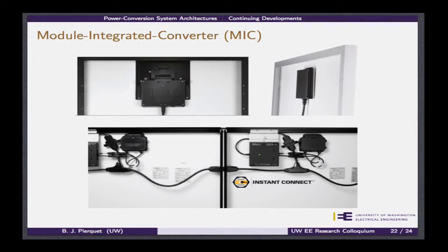So now, if you want to improve upon possible mismatches, you can deal with 20 cells at a time in series instead of 60. And so there's another benefit to going even deeper down into the module to prevent a bit more of the mismatch issue. Part of it being that you can now probably make modules that don't have the same cells from the same bins.